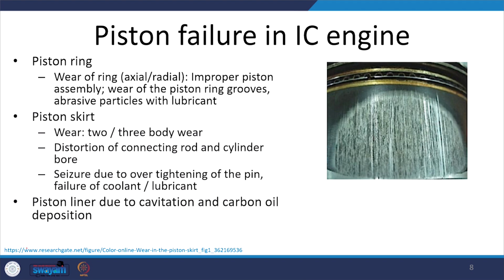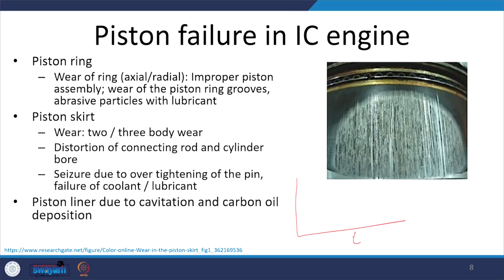So, this is how we can understand the two body and three body abrasive wear. Usually, if the abrasive particles are too much and they remain there for long due to any reason, then that will be increasing the rate of wear. So, wear rate, if we see as a function of the time, the wear volume, in terms of centimeter cube, that will be increasing gradually under the steady state condition.